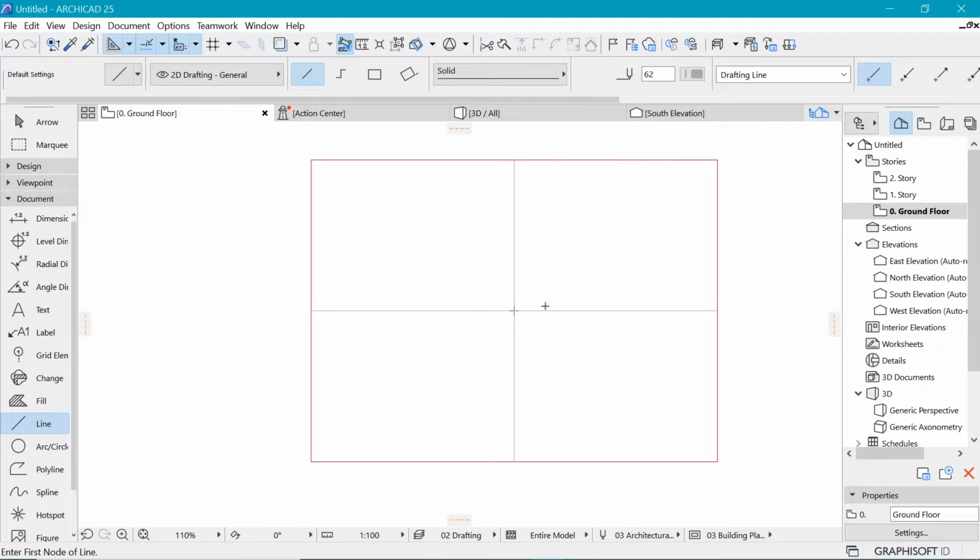Now we want to demarcate other spaces which are within these 4 spaces. For example, we are going to create here a washroom, and as well in these 2. For that, let's pick this one, and in order to pick it, there's a tool for that, which is the pickup parameters. If you click this on the standard toolbar and click on this line, you should be able to pick it. Once you do that, you can now draw with that red line. This washroom is going to be 1.5 by 3 meters. All right, so that's what it's going to look like.